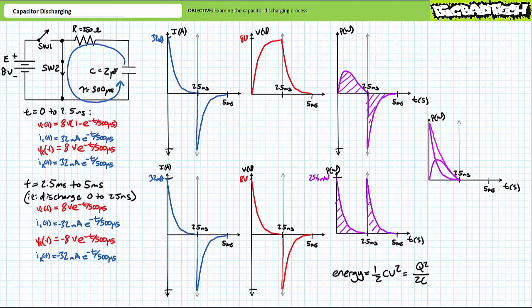While the quantity of energy dissipated by the resistor goes towards the production of heat, the quantity of energy consumed by the capacitor goes towards the establishment of an electrostatic field between the plates. Rather than using the term dissipated, it might be more appropriate to consider any energy consumed by the capacitor as absorbed or stored energy. It's essentially a spring coiled and ready to bounce. When the discharge process unfolds, the energy stored in the capacitor plates is released, returned, or better yet, supplied to the system. All 64 microjoules supplied by the discharging capacitor is dissipated by the resistor.